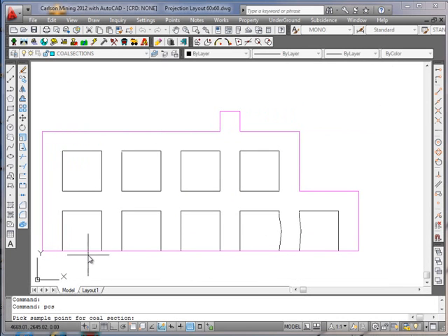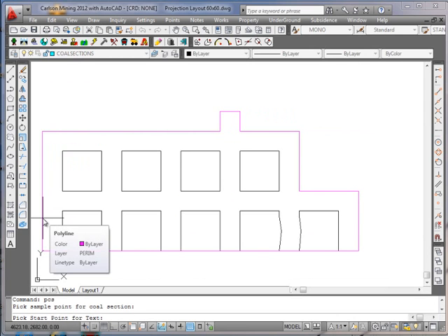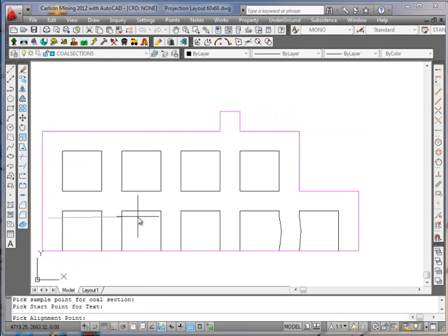And we'll pick a sample point here along this rib, and a start point for the text, and then we'll slide on over to indicate the direction of the text. And then we'll start populating. Typically you'd have field notes at this point to go from. So if we said 3 inches for the roof, 24 inches for the upper split of the coal, 6 inches for the parting, 24 inches for the lower split, and 3 inches for the floor. That might be a typical example.